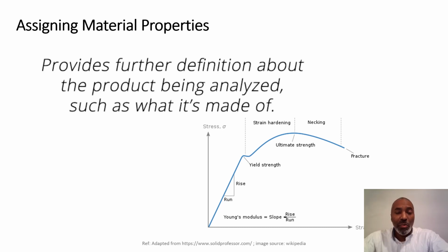Why? Because if you want to know what happens to something while it's failing, imagine a crash test or an impact test for a car. They're running these things from the car is perfectly fine, the car is moving along, then it impacts something, and it's going to go straight through that linear region, straight through yield, possibly into the strain hardening, and then up to the ultimate strength. So we need to know what happens over the whole range.